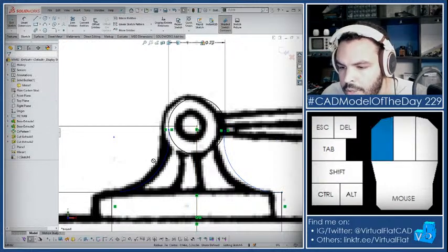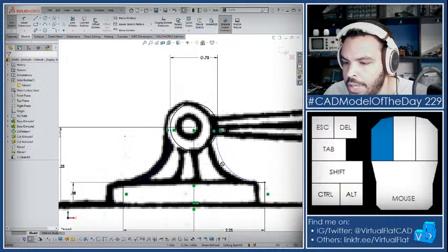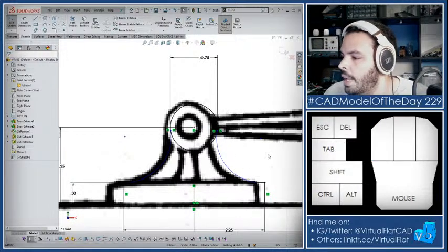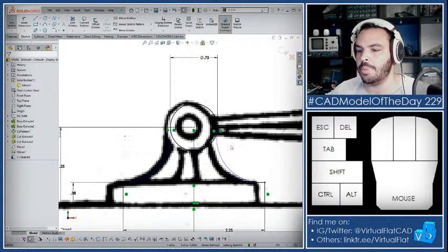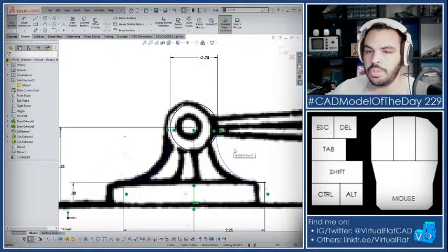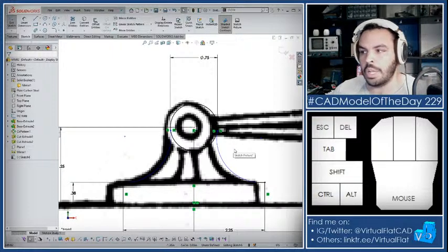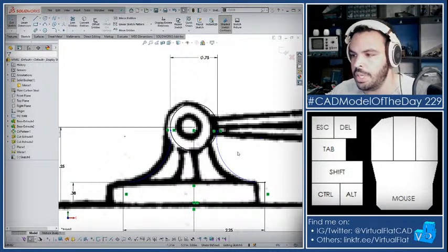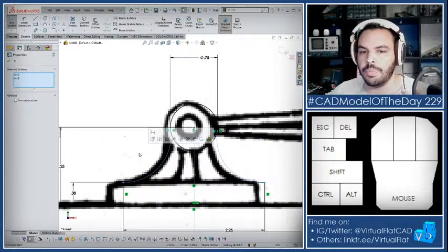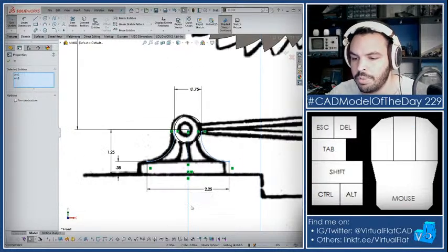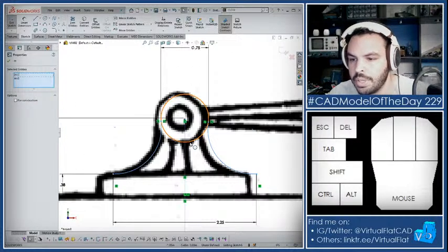And you can set... oh yeah, so I tried to draw a box. You see it says no. And that's because I'm trying to draw a box over the sketch picture, and it counts that as geometry. There's actually a solution for this, and in SOLIDWORKS 2018 Plus, if you press your T key on the keyboard, so I just press T, you can actually select over geometry, and that is super helpful for selecting basically selecting over sketch geometry.